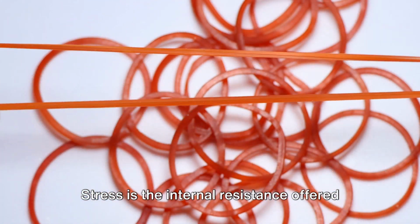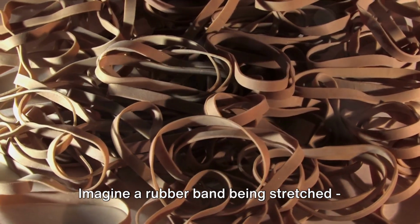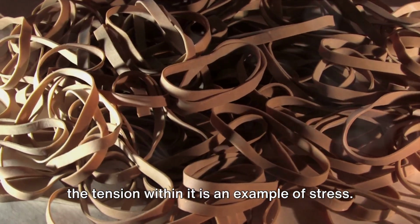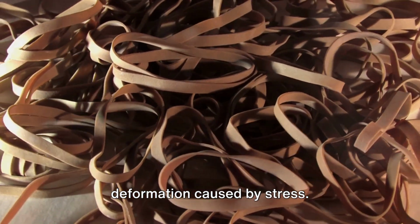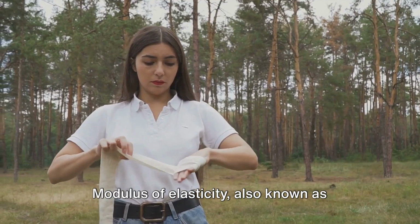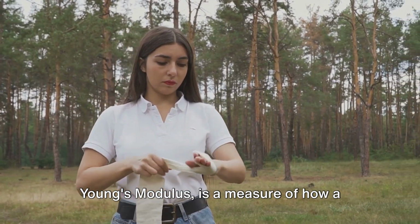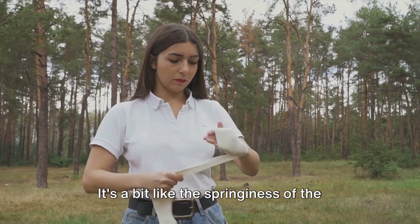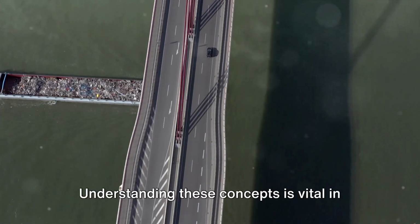At the heart of mechanics of materials lie three fundamental concepts: stress, strain, and modulus of elasticity. Stress is the internal resistance offered by a material to an external force. Imagine a rubber band being stretched. The tension within it is an example of stress. Strain, on the other hand, is the deformation caused by stress. In the case of the rubber band, the stretching represents strain. Modulus of elasticity, also known as Young's modulus, is a measure of how a material will deform under stress. It's a bit like the springiness of the rubber band, how much it stretches under a certain amount of force.